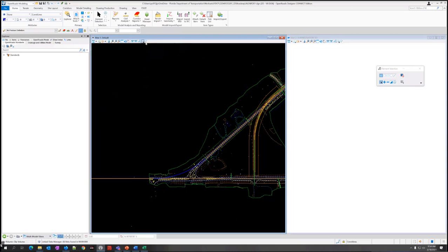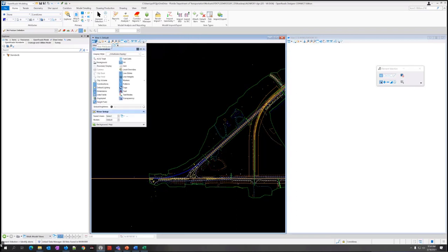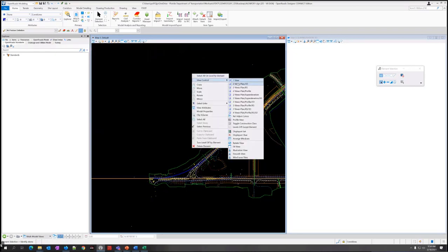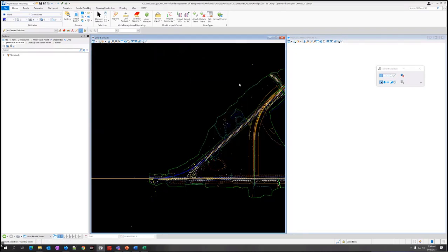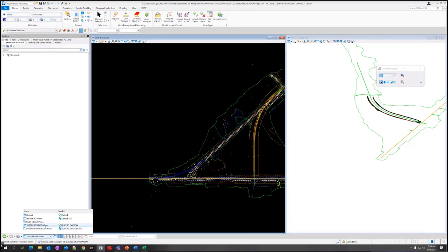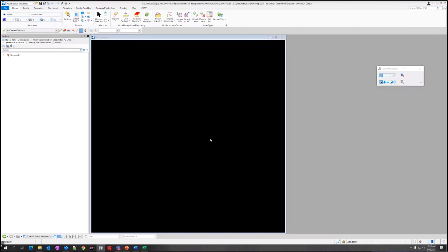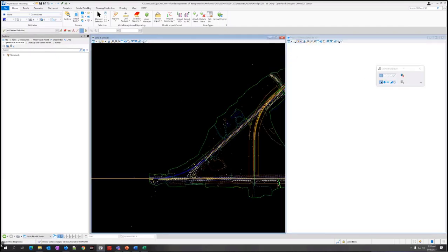So what I can do, if I do that, F2, that's fine. Just got to keep in mind that that's a limitation of those shortcuts as well as the shortcuts here on these view controls. Plan 3D is going to do the same thing. It's going to be default. Well, actually, it's default 3D on that one because it switched over to default. So I'm going to do F2. This is super elevation 3D, and over here is default.